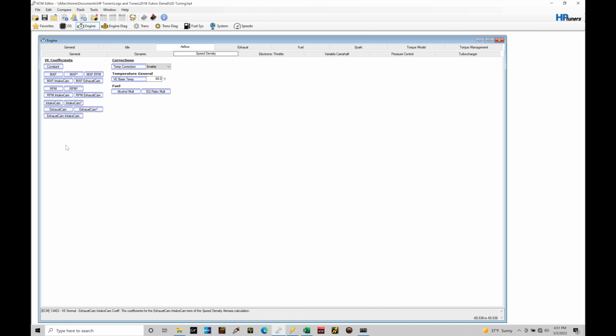What we want to find is that at any given operation point, whether we're measuring the amount of air mass coming from our mass airflow sensor or calculating the amount of airflow or air mass at that exact same moment, we should find that they line up together. That should make sense. There shouldn't be a deviation. Whether we're calculating or we're measuring it, they should be identical to each other, because air entering the engine is air entering the engine. So we'll find the way that the vehicle is going to be running, and all of the calculations that are performed in the background hinge upon having the airflow models matching each other. So our goal here is to make sure that our speed density is calibrated properly.